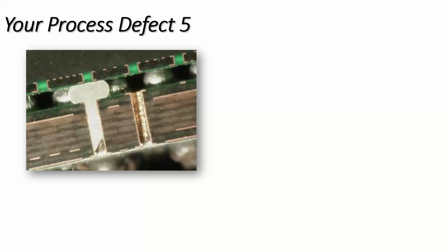So look at least at plugging vias with a solder mask, or plugging them in another way on the recommendation of your PCB manufacturer as a process, but don't leave larger via holes open if you're going to be doing wave. If you're doing selective, then theoretically you shouldn't be soldering this particular point of the printed circuit board in the first place. So it shouldn't really be an issue for selective, but maybe for wave soldering.